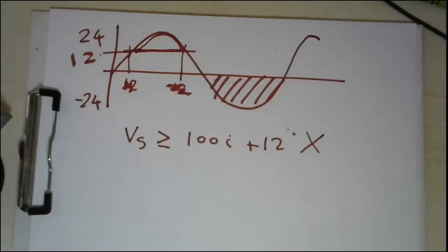So this is a new example for a circuit based on a diode, where we treat our diode as a short circuit whenever it's forward, and as an open circuit whenever it's reverse, which is what we call an ideal diode.